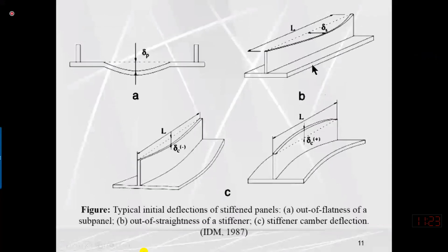And then we are having some other type of imperfection other than loading. These are referred to as initial imperfections. When I talk about initial imperfection, initial means that before the load is applied, the member was already imperfect, in terms of geometry and in terms of structure. So initial imperfections are of two types. Number one, geometric imperfection, and number two, we will see in the next slide, structural imperfection.